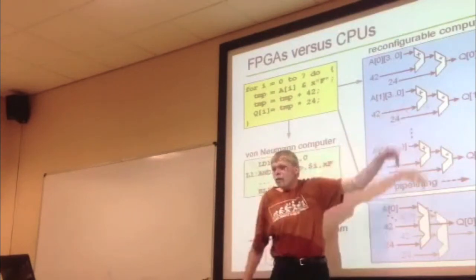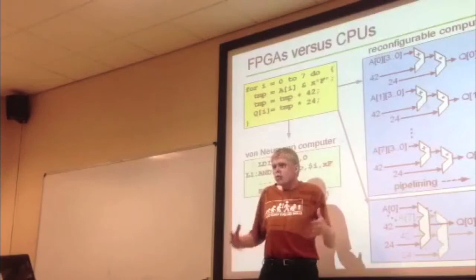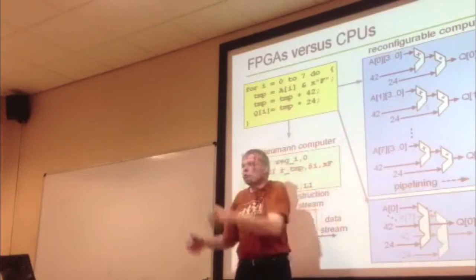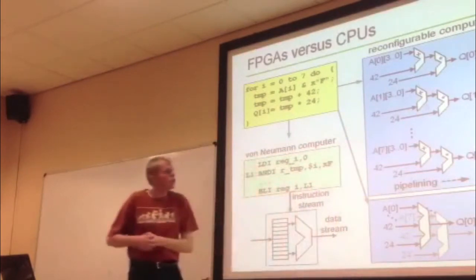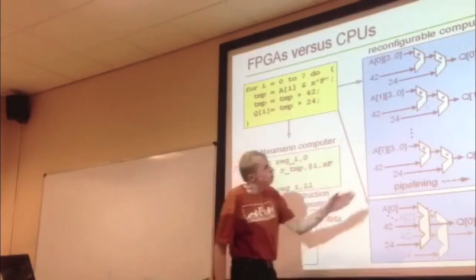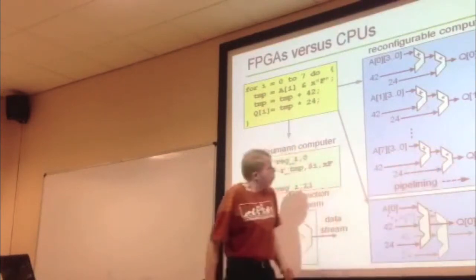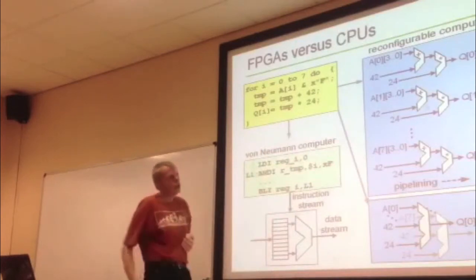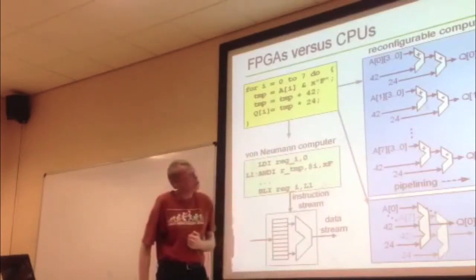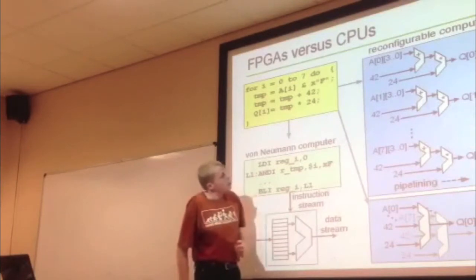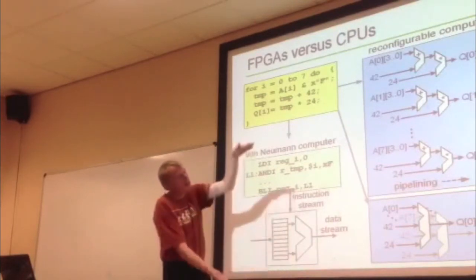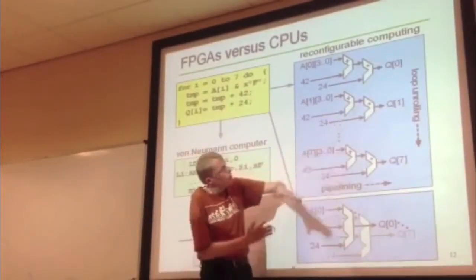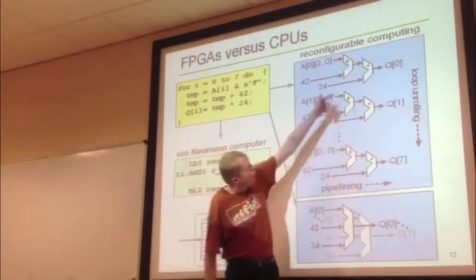Some things you just do in the packet. Data movement is not a move instruction. It is just a link or some wires you route between different functional blocks. And then you can put your adder, your multiplier, and so forth, and you can build a pipeline in that direction. But that's one thing. You could also exploit parallelism by instantiating it multiple times. So in principle, you could run the whole loop body in parallel and unroll it.